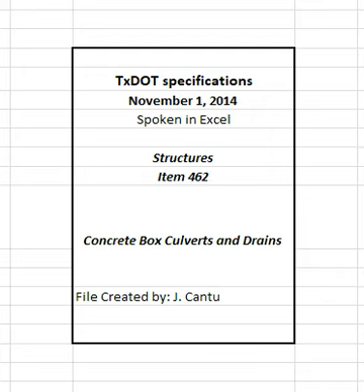Deviations from the above tolerances will be acceptable if the sections can be fitted at the plant or job site and the joint opening at any point does not exceed 1 inch. Use match marks for proper installation on sections that have been accepted in this manner.